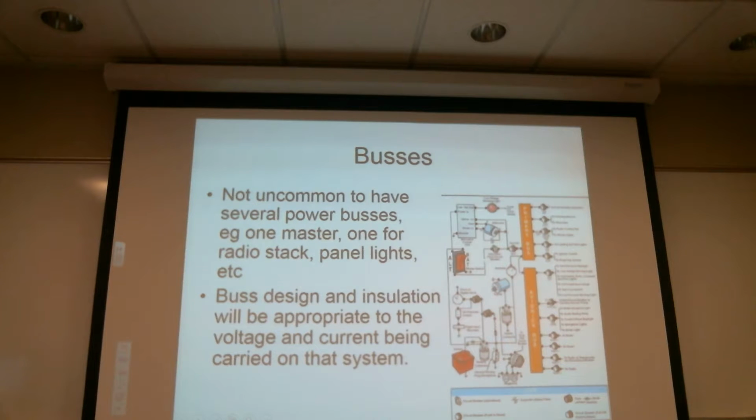It's also very, very common, particularly on larger airplanes and military airplanes, to have redundant buses. I've got bus 1 and 2 and an A and B on each one, and any one can be channeled to back up for the other. So if I do get a short and I have to shut one down, I can route around it.